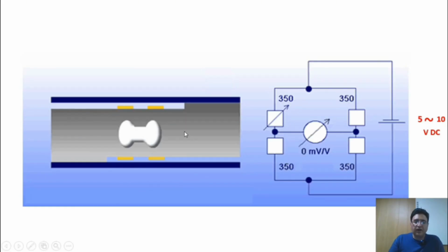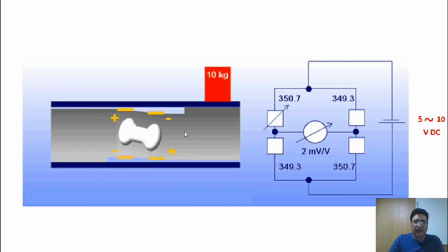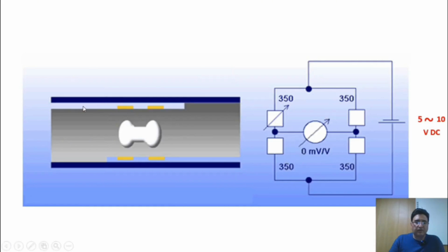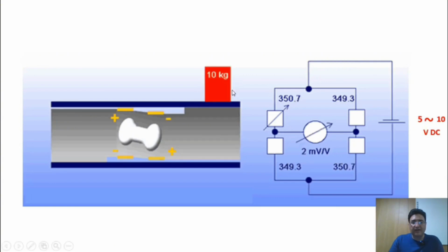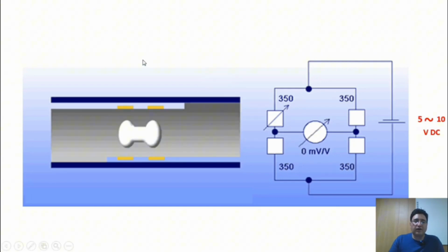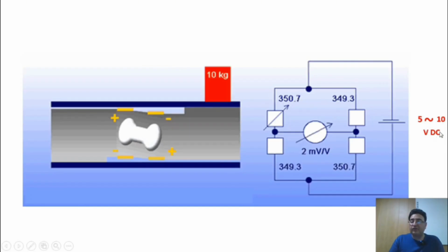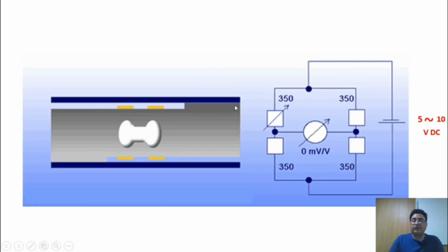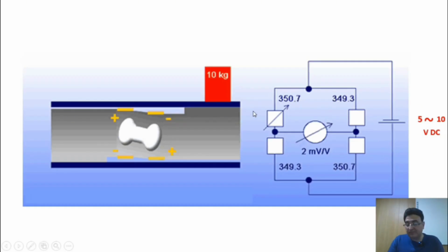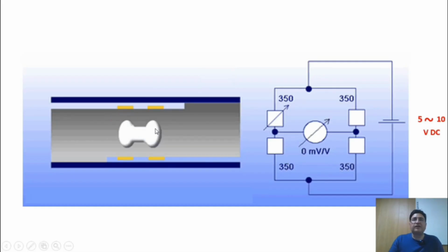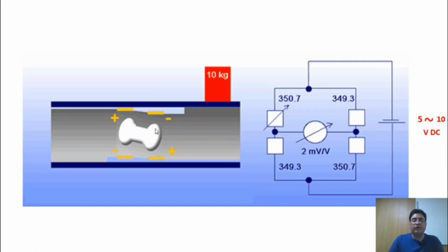In the case where our load cell is unloaded, the output signal shown by the load cell is 0, but when we place the maximum load, that is 10 kilograms, on the load cell and the voltage connected to this load cell is 10 volts, our output change will be 20 millivolts. So this 10 kilogram load cell can provide us with a signal between 0 and 20 millivolts.